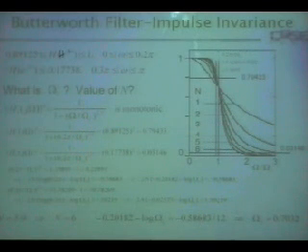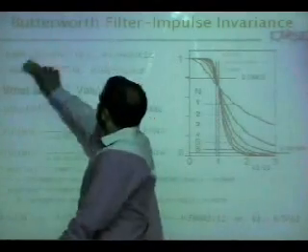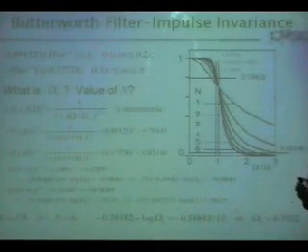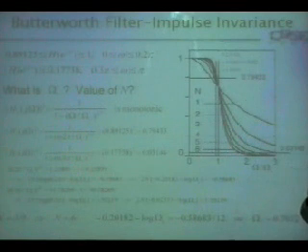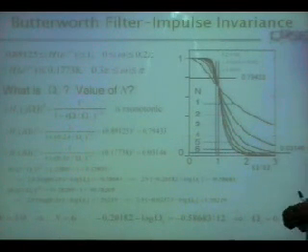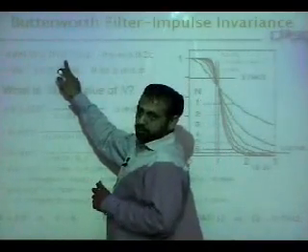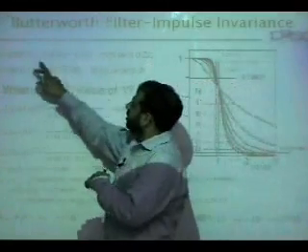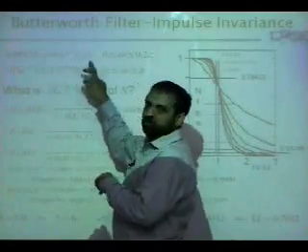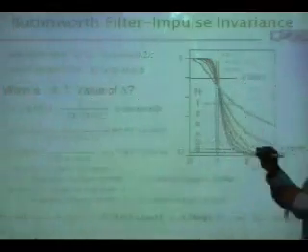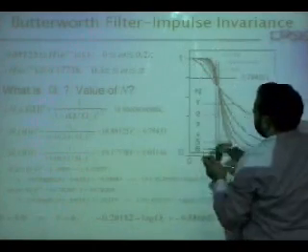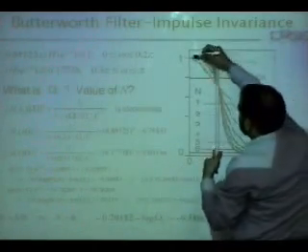Usually, as we know, you will be given design specifications. Design specifications are in terms of small omega, because I want to design a discrete time system. I give you a specification that I want this digital filter, but I say I want an IIR filter. I say I want a filter where the frequency response from 0 to 0.2 pi should remain between 0.89125 to 1. So this is my pass band ripple, that it should be within this range. It can ripple, but in Butterworth it does not.